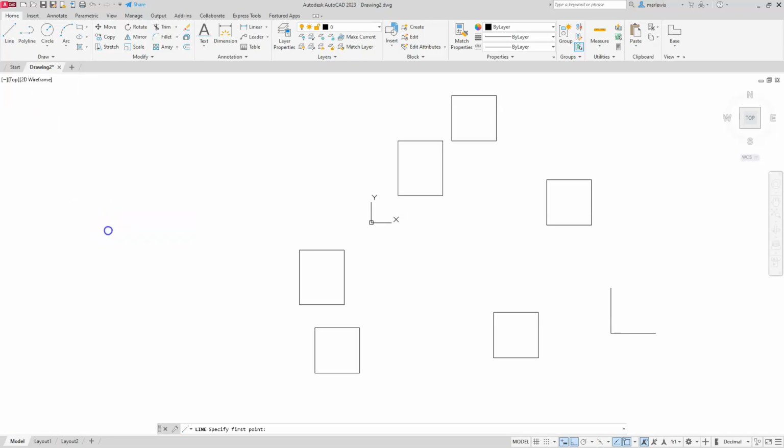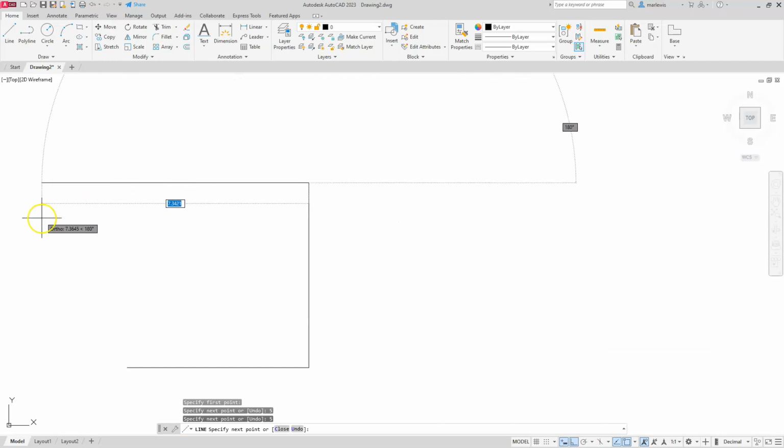So all of these boxes that I'm creating, the much quicker way of doing that is using a line command, select the first point, aim the direction. So I got the preview going this direction, type in 5, hit enter. You can see that my line is actually going up. 5, enter. I want to go to the left. I want to aim it this direction, as long as I'm getting that line to go that direction. And what I mean by that is that if you're not looking on your screen and that line is still pointing up in this direction, when I type in 5, it's going to add another line going in the up direction at 5. So make sure that you're taking a look at the preview, and I'm going this direction, and I type in 5, enter, and then c to close. All right, that is super useful if you're creating things that are orthographic.